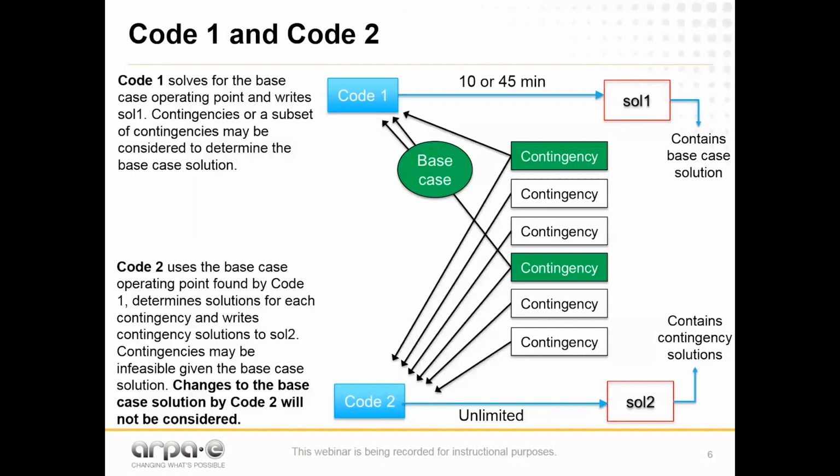Okay, so if that's the question, all right, so that's basically a node in this network flow model. The value of the impedance of the bus, when you are solving these security-constrained OPF problems, is basically next to negligible. You have impedance values for transmission lines and transformers and other assets, but the bus itself does not have a representative impedance value.